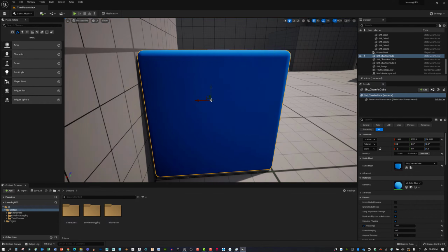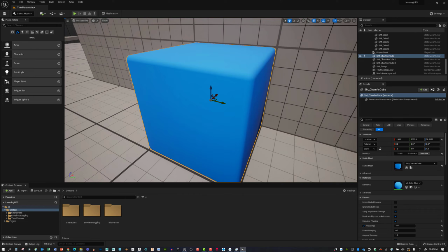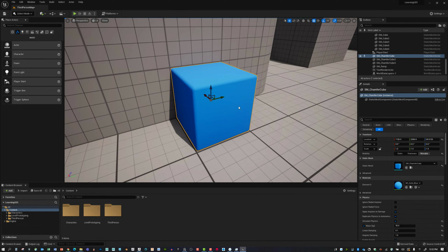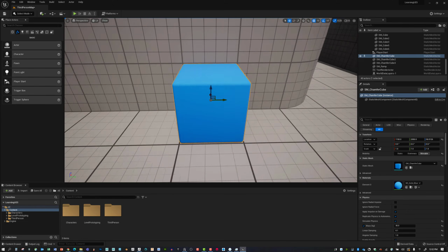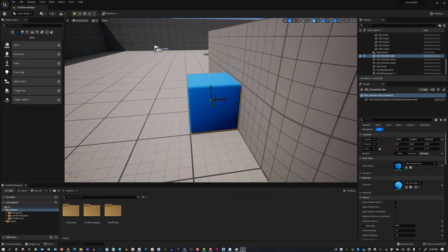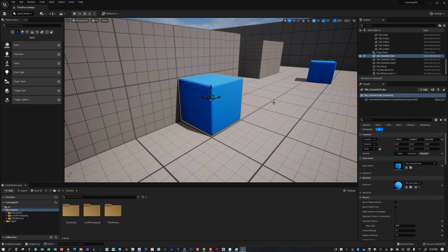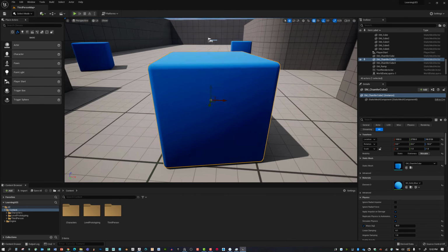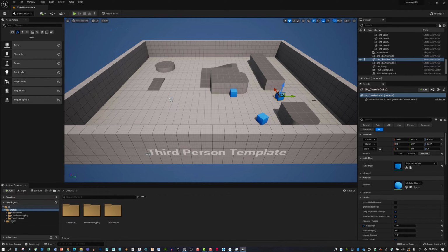Now, this Maya method, I definitely use that when I'm selecting an object and I really need to have some focus on that. I like to select it, tap F, and then hold down Alt, left mouse, right, and that allows me to inspect that element and then go to it pretty quickly. Also, if we have those camera views stored, if you need to get to an item pretty quickly, probably the fastest way is just select it and tap F, and you can frame in on that thing and then rotate around. Okay, so that's navigation, and then you definitely want to practice on that for a little bit.